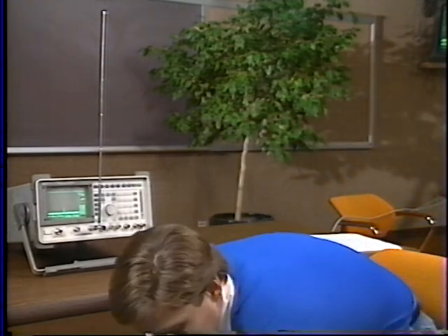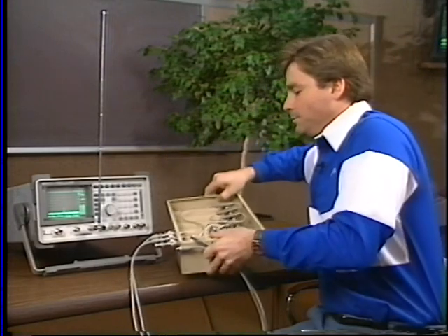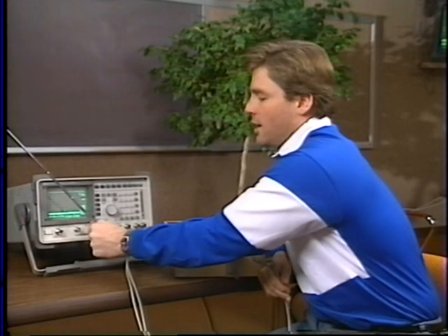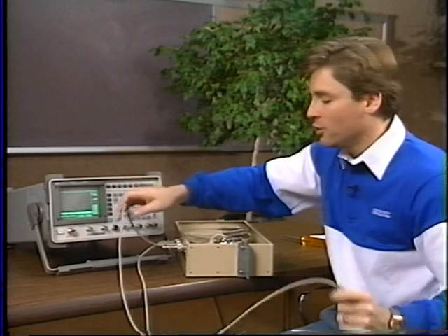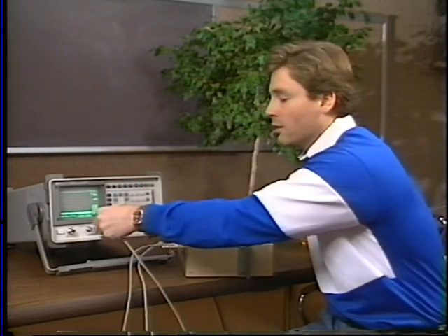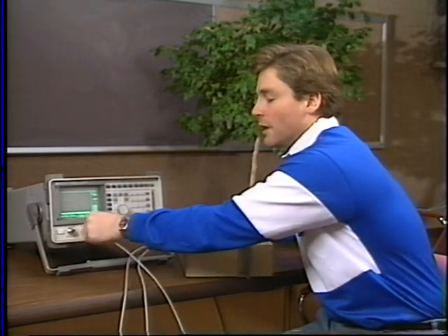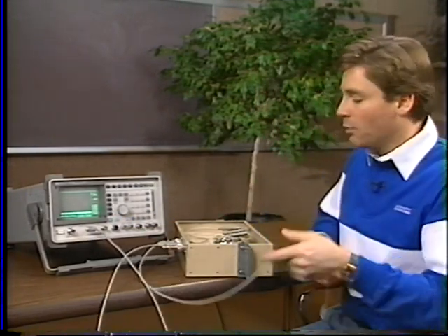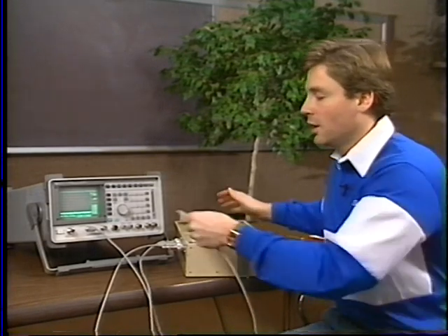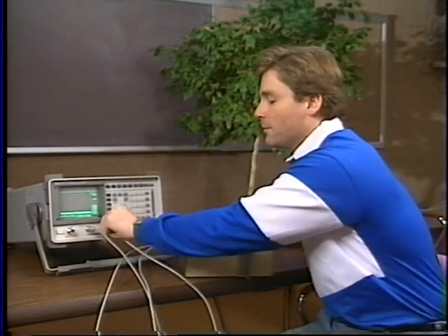Now let's use the built-in tracking generator with the spectrum analyzer in the 8920 for making a swept response measurement. For this example, we'll use a radio duplexer to do our measurements. First, we'll take the antenna off of the front panel of the 8920, and we'll connect the antenna input to the duplexer up to our RF generator, and we'll route that out of the duplex output port. We'll take the output of the duplexer and put that back into our antenna input so that we complete our two-port measurement.